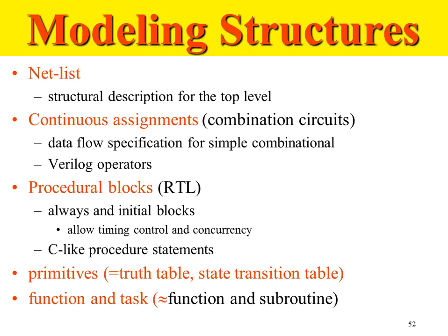Okay, so modeling structures. Now, modeling, or Verilog, as you might remember, we saw the history of Verilog. It started out as a modeling language, and then synthesis was invented, and we could convert a Verilog model to hardware. So modeling is a word used quite frequently. It means design also. That can be done using various syntax or various statements in Verilog. One is a netlist. You can create a structural description of the design like we just saw.